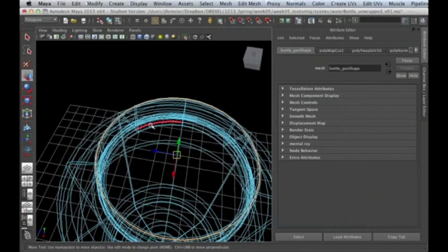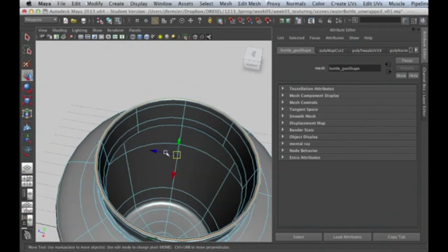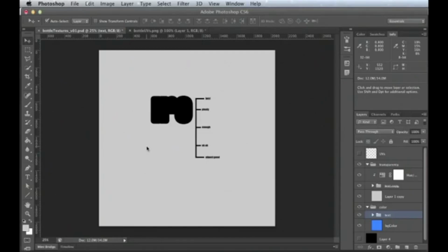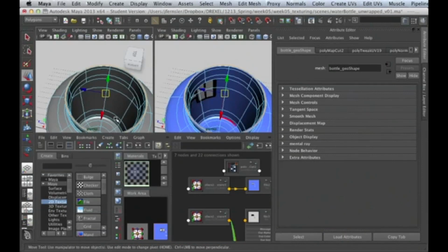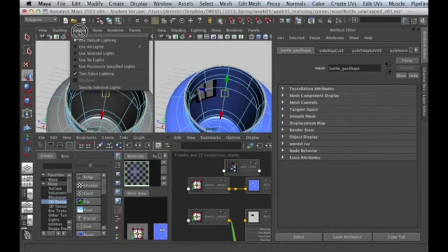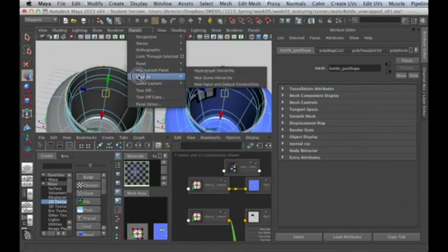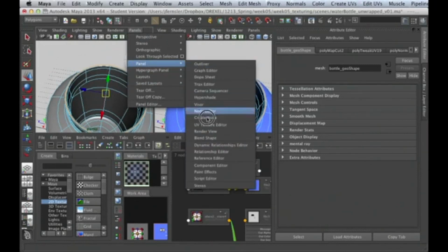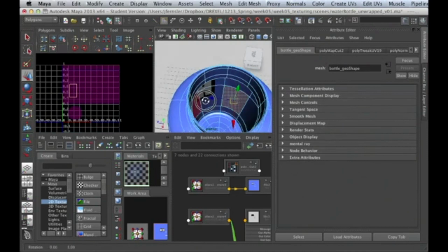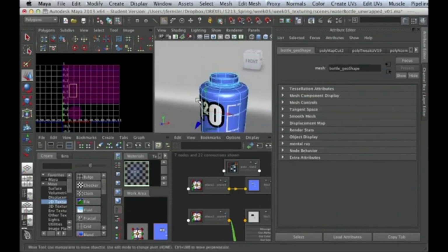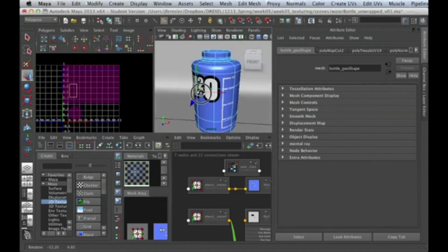And take my word for that. Here's the way to check it. Here, we've got a lot of overlapping UVs. Oh boy, I'm going to do panels, UV texture editor. Oh, everything's overlapping, so it's going to be difficult to select a shell here. I'm just going to do a quick face selection on the inside. That's just the inside face, okay? One face on the inside selected.